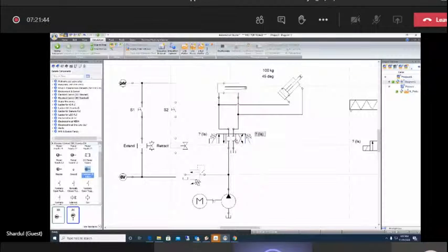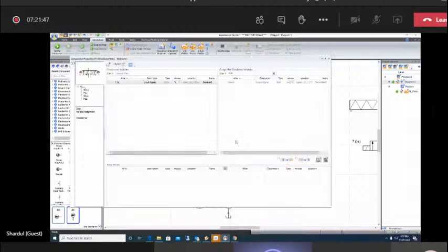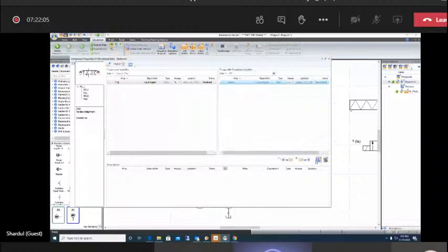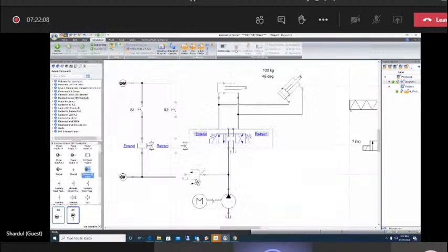Directional control valve, and I click on the left solenoid, so I have something for variable assignment. So I will just link it to the solenoids of my electrical part. I have named the second solenoid as retract. I can just type here retract. The software will automatically give me the solenoids here. So if you see now, there is a blue color appearing for the solenoids. That means these solenoids are hyperlinked. If you just control plus click on it, you will see that these are hyperlinked.